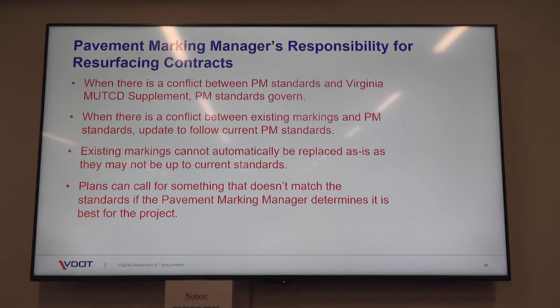Recognizing that there could be an increase in cost and life cycle costs in doing so, but we do need to make sure that we're bringing all of our roadways up to standard. There's a cost associated with proper eradication of unnecessary markings. That's why it's important that we put them out correctly when we're resurfacing. We don't want to have to come back after the fact, realize that it's incorrect, and eradicate. Eradication is expensive. Improper eradication or maintenance can lead to the material failing. So it is the responsibility to get the markings in there correctly the first time.